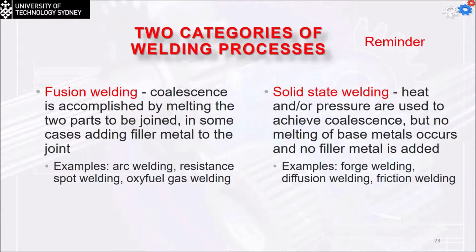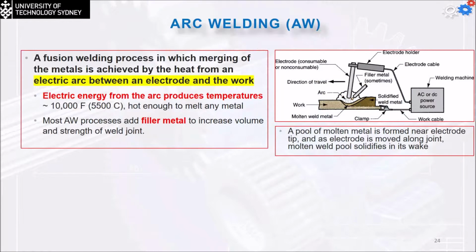Now, the first type is arc welding. I think you saw this machine before. Again, to have the arc, it runs a high current, and this causes the high temperature to be achieved. And thus we can sometimes add the filler metal to get melted. We say sometimes because sometimes we're only melting the 2 base metals and leaving them to cool down.